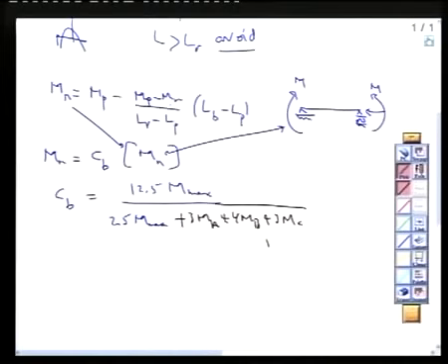And this should be less than or equal to what? What is the largest value of Mn? Mp. Notice in columns we said that the largest value is Fy as a stress. In bending moment, the largest value of Mn is Mp.